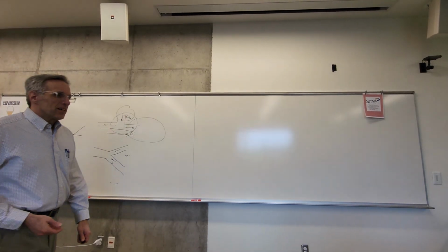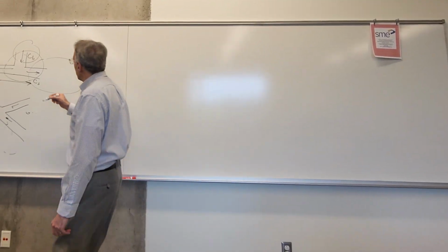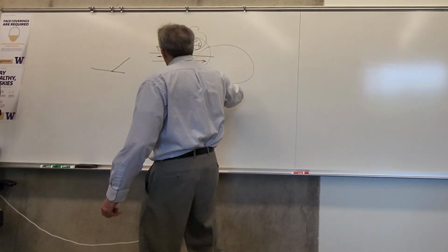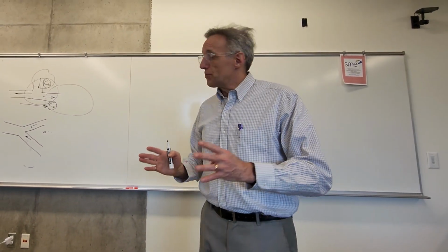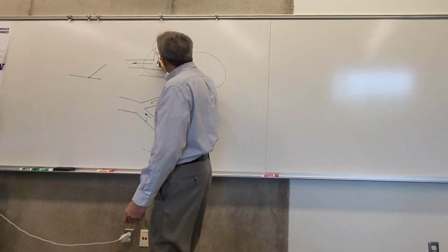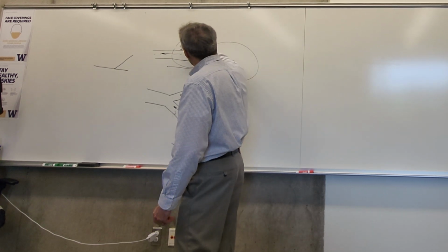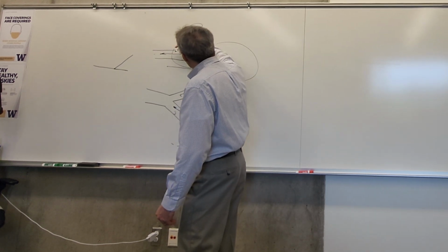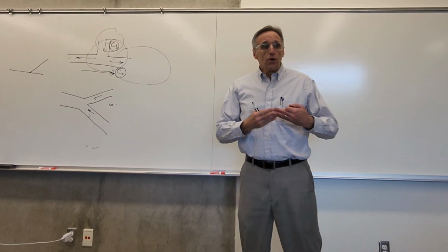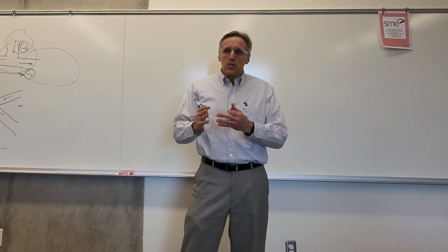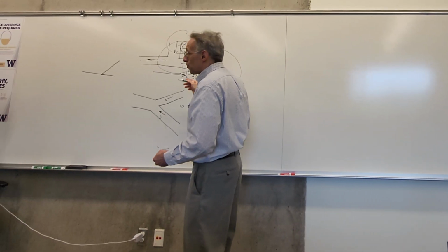And it's actually quite cumbersome to do by hand because you have to calculate these; they are not given. These are based on characteristics of the piece of duct itself. So you have to go and look for a T fitting, and it's a full flow T fitting versus a T fitting where one section of the pipe is much smaller than the other. But there are standard fittings, and you look them up, and I think they have some in our book at the end of the chapter, and they'll actually tell you how to calculate these loss coefficients.